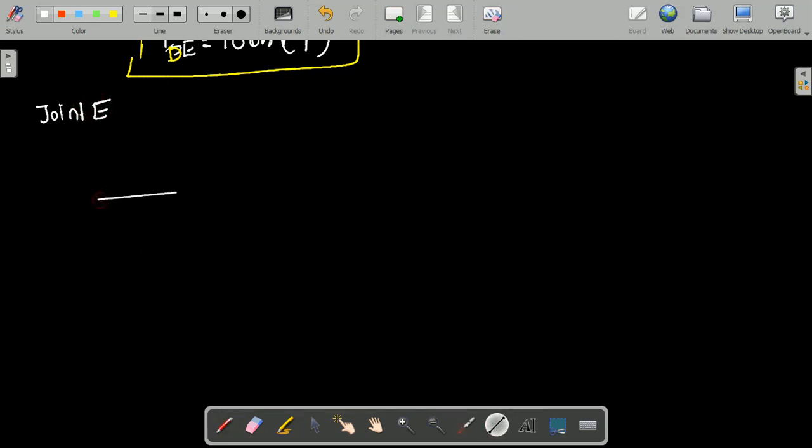Just now I have shown, I am going to write the free body diagram. From point E we are having TEF, and TED, and TEC. Okay, this is one force, and this is one force, and again from this we are having one force, just as I have shown in the figure, and another force which is 1000 moving downward. 1000 is a force acting at point E, and TEF is another tension member, and TED is there, and this is TEC. Now you can be clear with this.